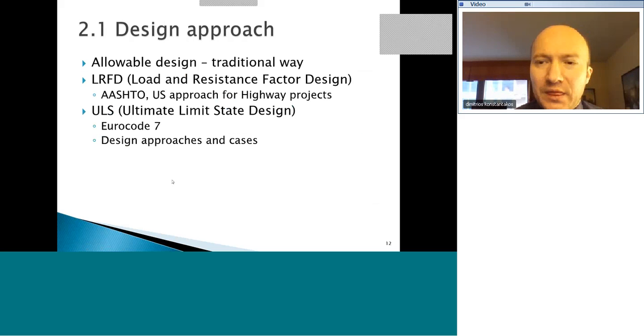Now, there are different ways over the years of designing deep excavations. The traditional way is the allowable design, where we're assuming some safety factor on the capacity of the systems, and we conservatively assume soil properties. We'll look into that. Another way in the US is the load and resistance factor design, LRFD.